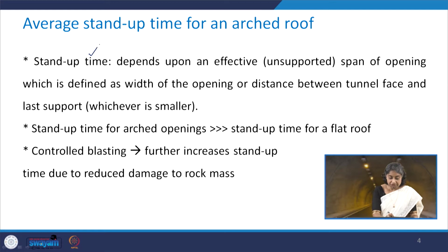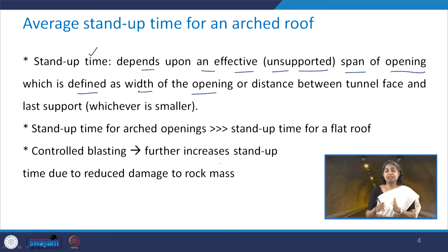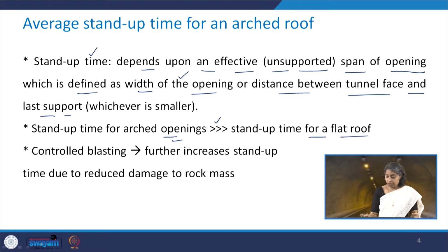So, this stand up time basically depends upon an effective or unsupported span of opening, which is defined as the width of the opening or distance between the tunnel face and the last support, whichever is smaller, whether the width of the opening is smaller or the distance between tunnel face and the last support is smaller. The stand up time for the arched opening is much larger as compared to the stand up time for the flat roof. So, how does it look?